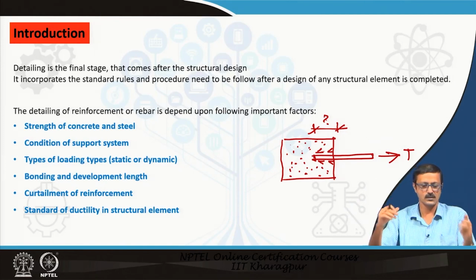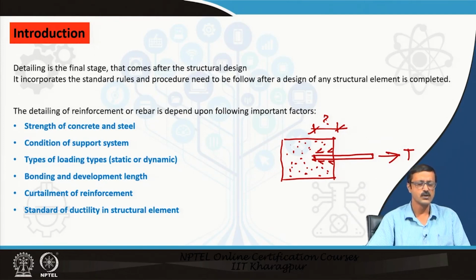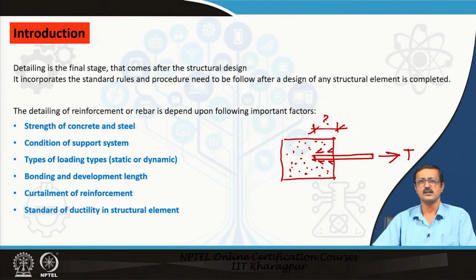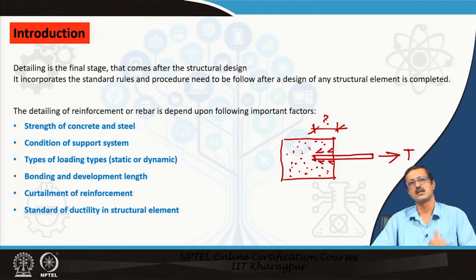We have not discussed that in detail, because that comes purely under the civil engineering domain, so we do not bother about that. The civil engineers and the structural designer will help us to calculate, and from the code they will find out how much the development length is. But we should know that sometimes excess steel is given, and that is due to the development length or so.